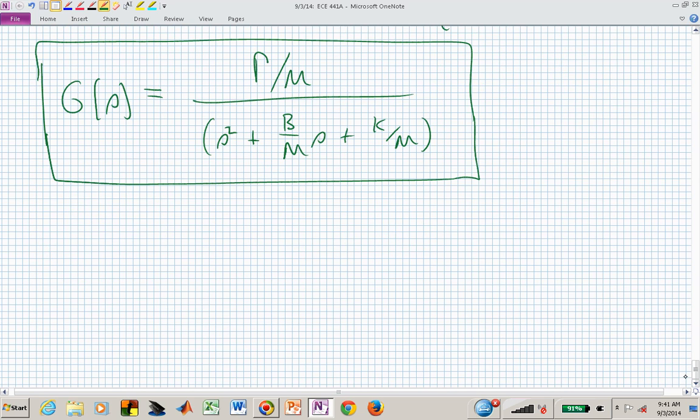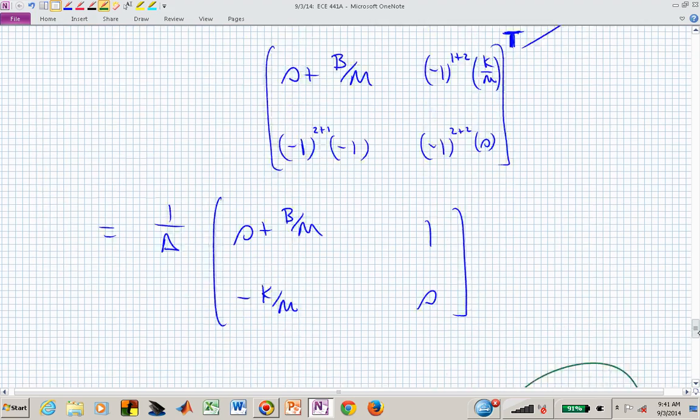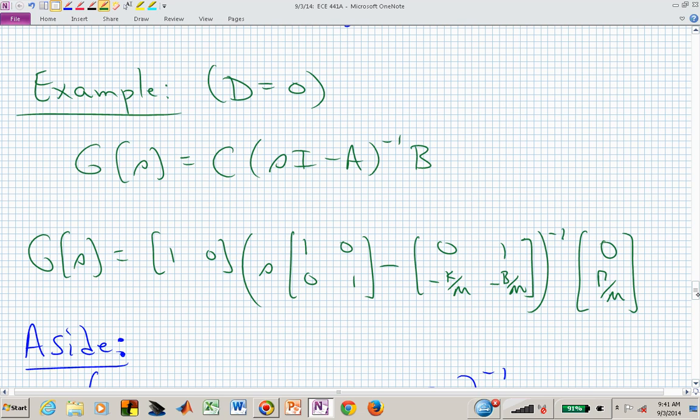we had in the other two cases where we were starting initially with the differential equation, and the second case we were working with the transfer function, with the block diagram, and here we have generated or completed our discussion of finding transfer functions by going from a state space representation, which was the c times si minus a times b, and the d was 0.